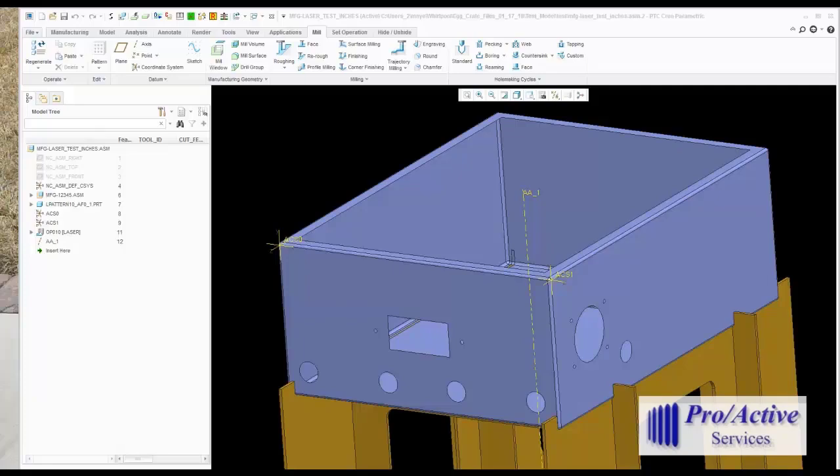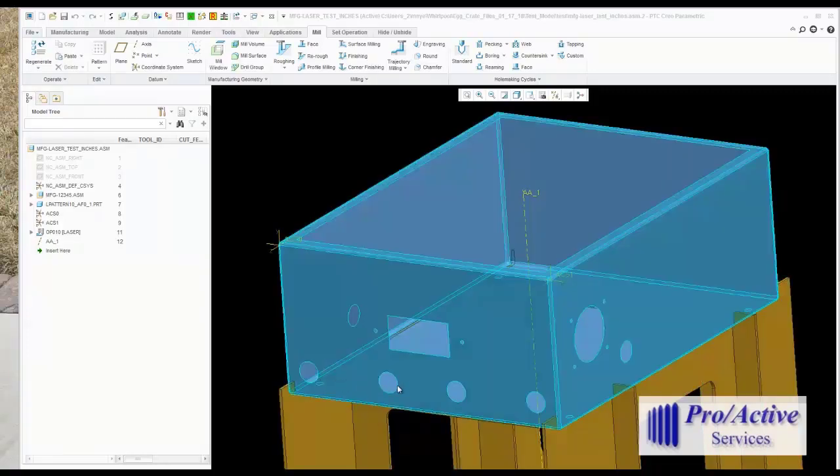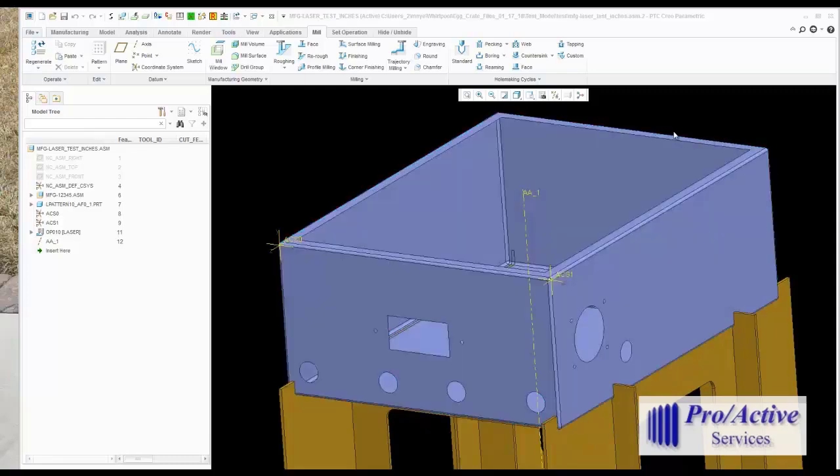I'd like to give you a quick example on how we can use Creo NC to cut this part. I'm going to create some positioning moves to cut some of the contours on this one face on the front, on the right hand face. Then I'm going to make a cut that will basically cut this top lip off the part, progressing around the part. I want to show you different methods of controlling the tool axis.